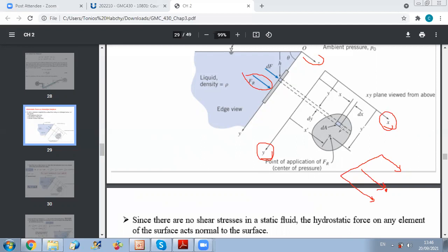So I should find the location of Fr anywhere to have the same resultant moment of the distributed load about X and the same resultant moment about Y. Okay. Now, concerning the moment sign, if it's positive or negative, all you have to do is apply the right-hand rule.